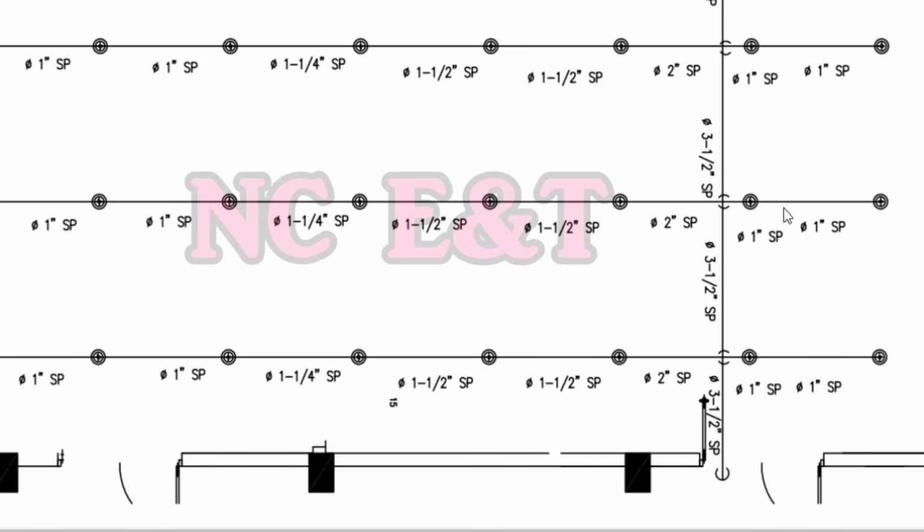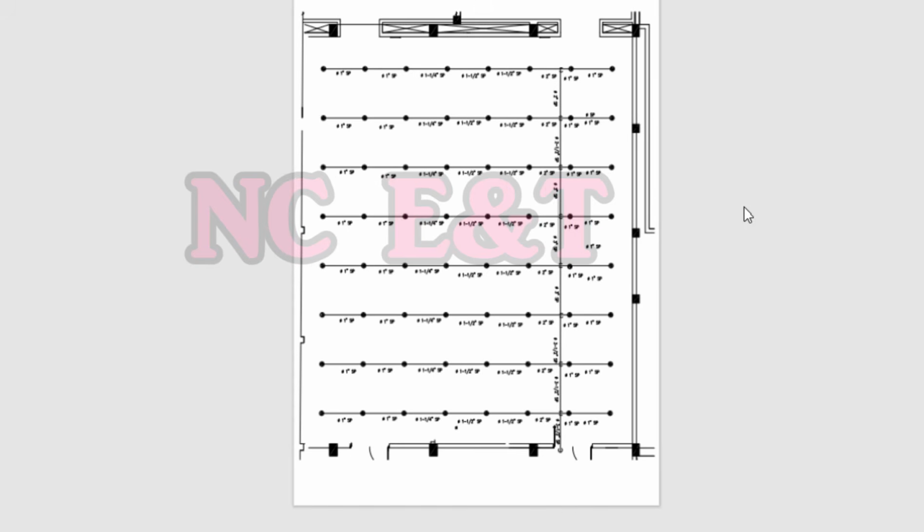So you have seen that in this way we can select the pipe sizing using the pipe schedule method of NFPA 13. First we made the calculation to find the location for placing the sprinklers in the room.